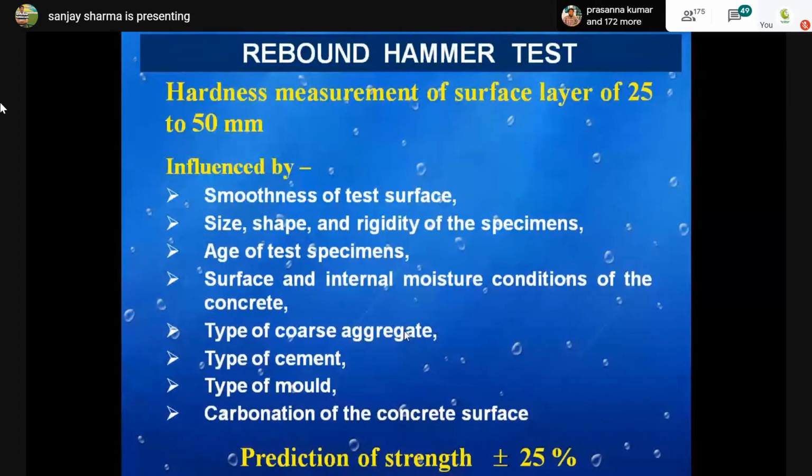Another thing in any non-destructive testing is that we first have to reach some sort of agreement between the parties on what the acceptance level is, and whether simply going for a rebound hammer test is sufficient. If we are checking, say, 100 locations, and 80% of locations are found okay, or the variation is within a certain percentage, we say okay.